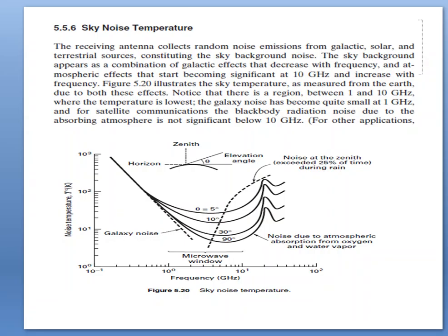And the lower curve represents the most benign case. The figure shown is the plot of noise temperature versus frequency due to rain. Since the intensity of any rainstorm can only be expressed statistically, the noise temperatures shown are values exceeded 25% of the time. Which spectral region appears most benign for space communication? When rainfall is taken into account, it is the region at the low end of the space window.